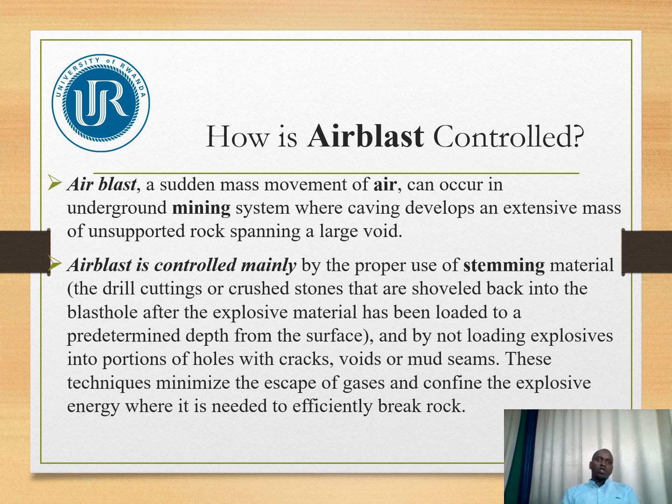You need to make sure that the energy of those blasting materials is strongly confined within the blast hole. So the air blast is controlled mainly by the proper use of stemming material.